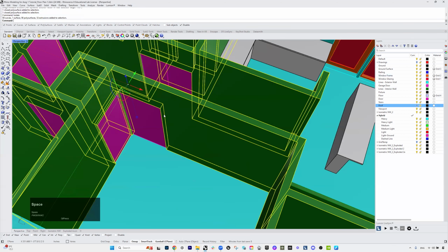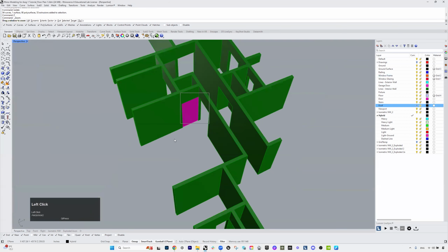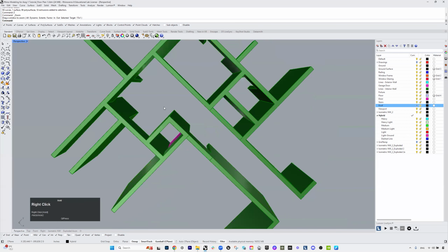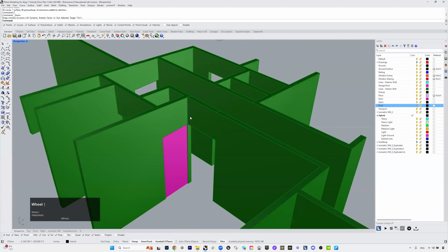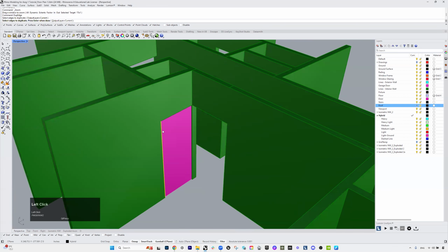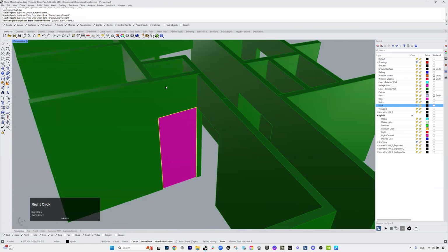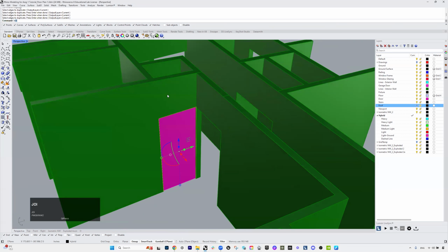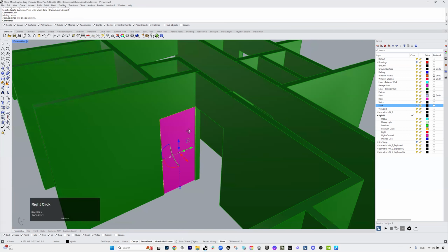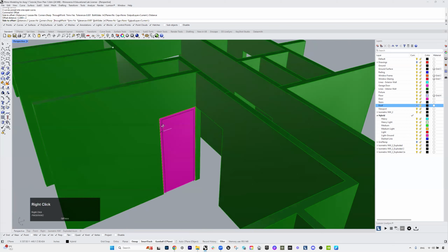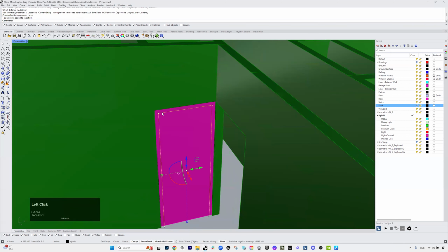I'm going to isolate this. Over here is the closet door. So I'm going to duplicate the edge of the door openings, kind of like this, and hit enter. And I'm going to join all these lines, so now this is one continuous line. I'm going to type offset and change the distance to 2 inches, and then offset towards the inside. So now I have this line and that curve over here.